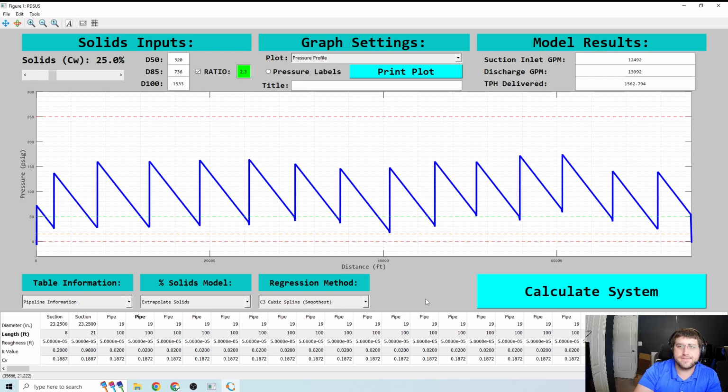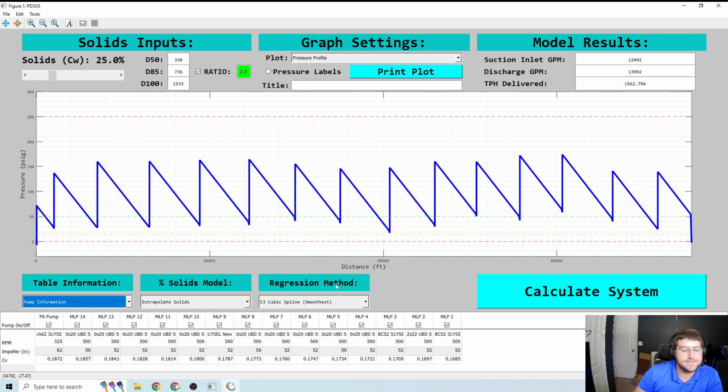Then you could say, okay, at this current state, my flow rate is this. How many sections change in X time? Put it forward. If you know your stuff coming in, you can set that back at the suction here and into these pipes. If you know your sealing water flow, you can dilute and move it forward, and then you get to your next state and get the flow rate there. And essentially, what you can kind of do is try to create a FEA simulator. It's not going to be exact, but you could say, okay, I have no water. I start sucking up this percent solids for X time, and then I switch. I'm now sucking up X percent at this time, and eventually, you could get something kind of cool going here. You could almost have a time-based simulator. So that's the next step, is to try to extend this into a simulator.